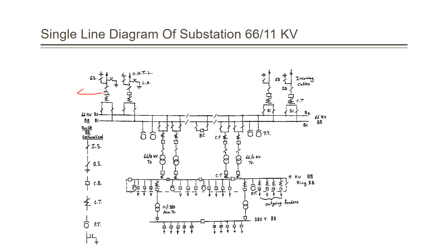As we remember, the circuit breaker is acting as the muscles, the one which switches on and off during short circuit. Here we have this symbol which represents our current transformer. The current transformer is used for measurement and protection. It is used to step down the current inside the circuit in order to measure the actual value of the current passing through or absorbed by our line.